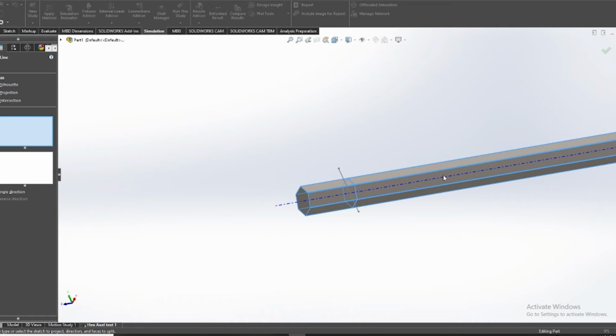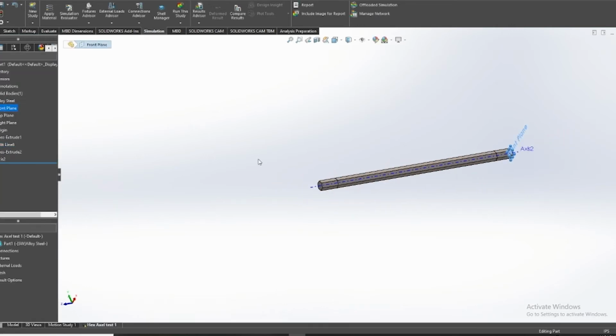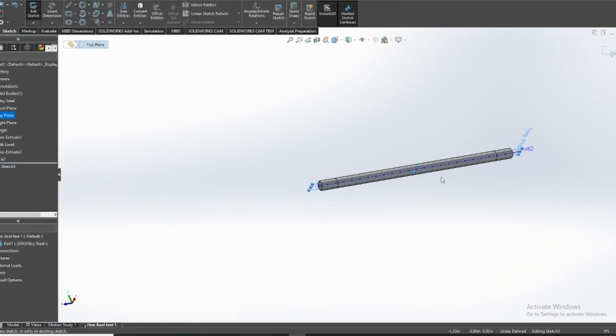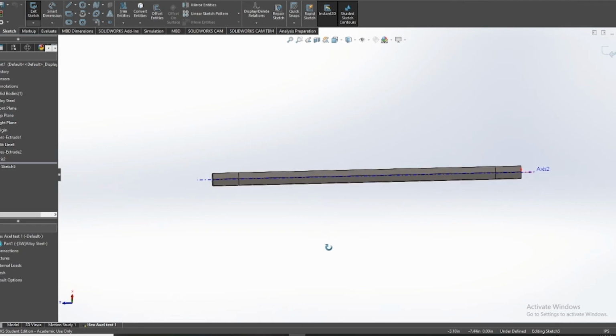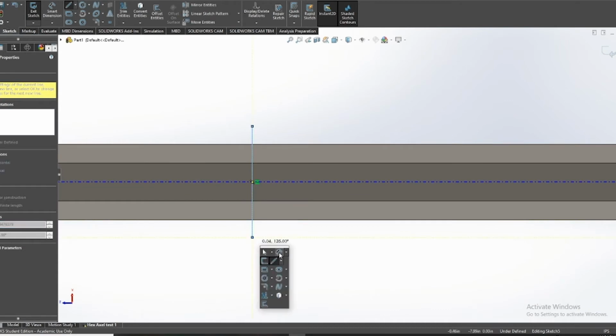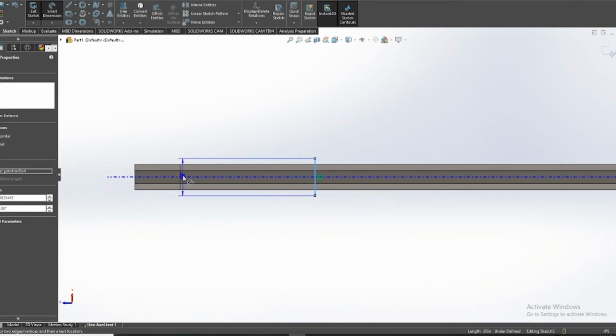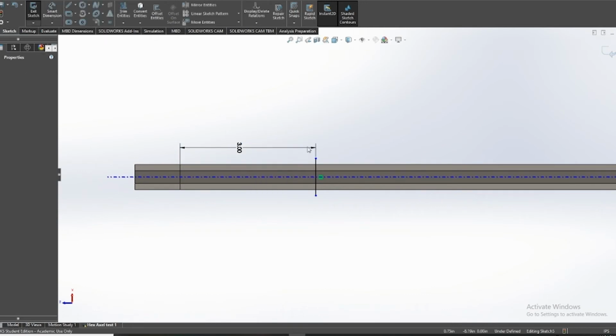We're going to do a projection, and I need to make a new sketch actually. So we're going to do it from the front. No, we're going to do it top plane. Top plane sketch. And then we're going to make a line down here. We're going to make it some arbitrary length from this, like, I don't know, 3 inches, because that was close.